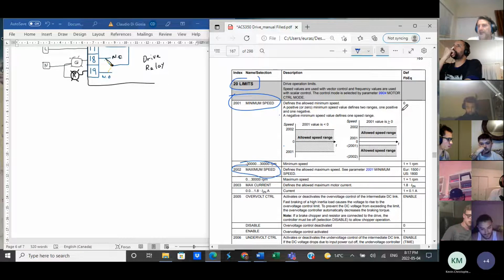Okay, so I'm just giving you some examples of where you would set it. Maybe you might want to set the minimum to 400 RPM, maximum to 1005. Okay, it's up to the user. You want to go 0 to 1725 instead of 0 to 60 hertz, which means the same thing? Go right ahead, but you can set the min and max speed.